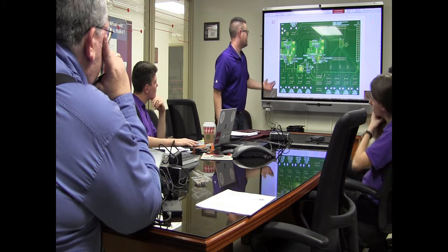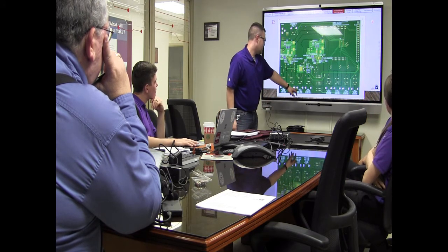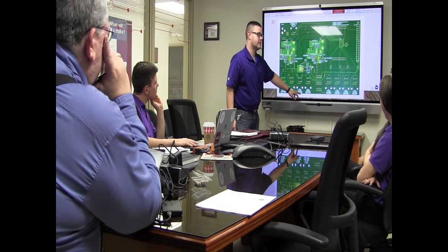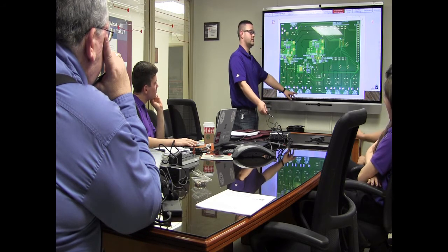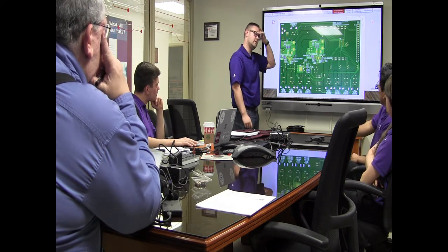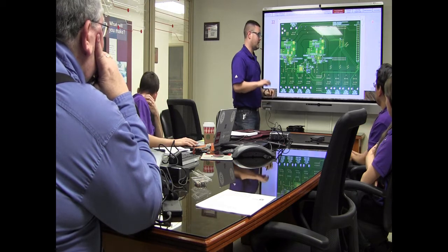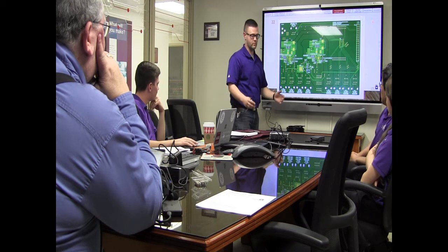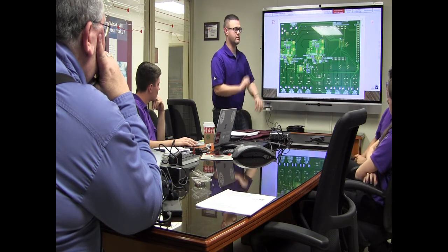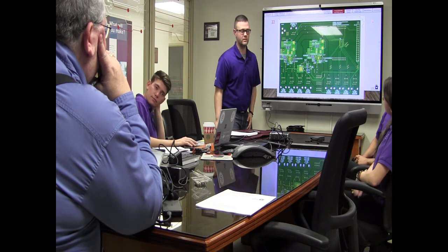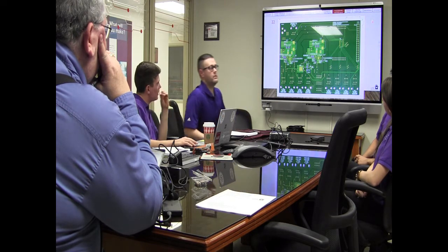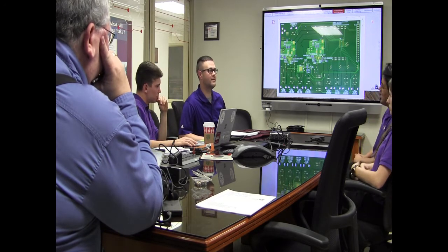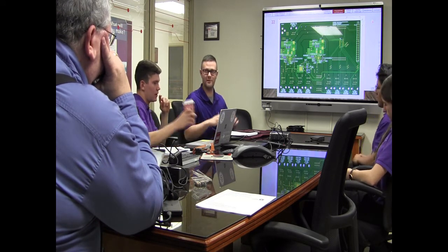something that was also super helpful was putting down what port number it actually is, what PWM number it is when you're programming it with the PCA 9685 in C, so that you can say, hey, this is the line that I want. I want pin 6 to be driven high or low, whatever the case may be. It's exactly how you can program it. It's been super helpful, and I wish we'd done it in alpha, because when we go back to working with the alpha board, it's a little harder to do.